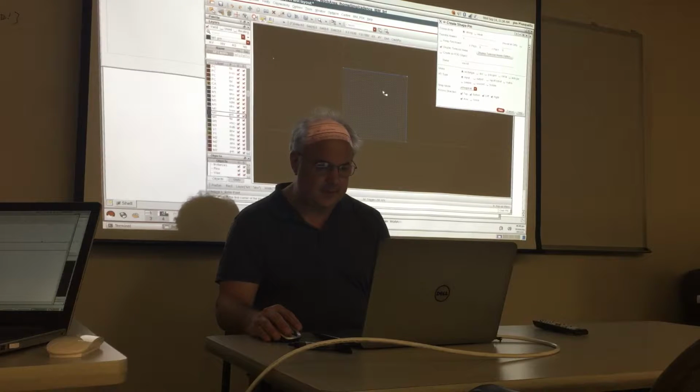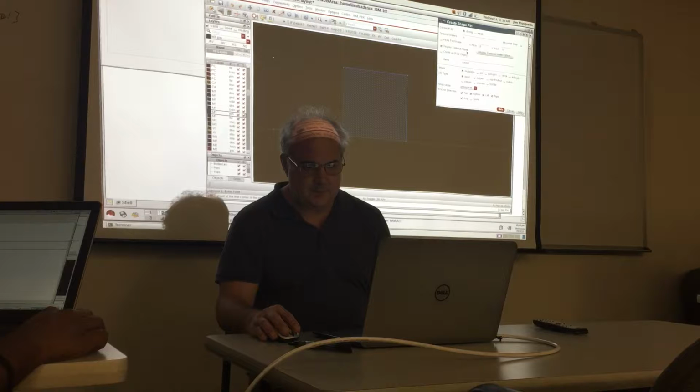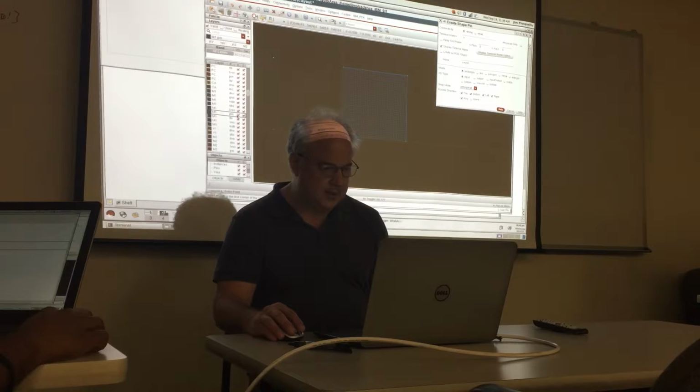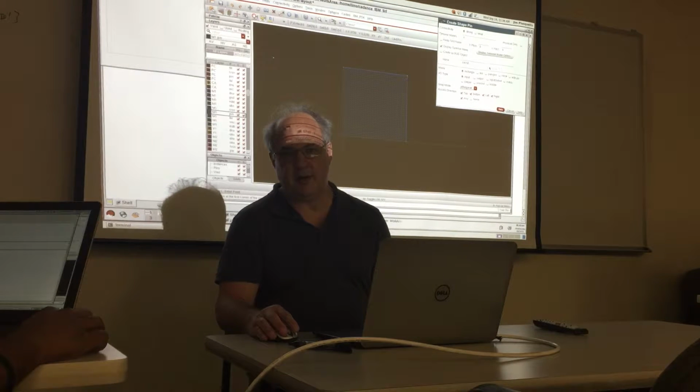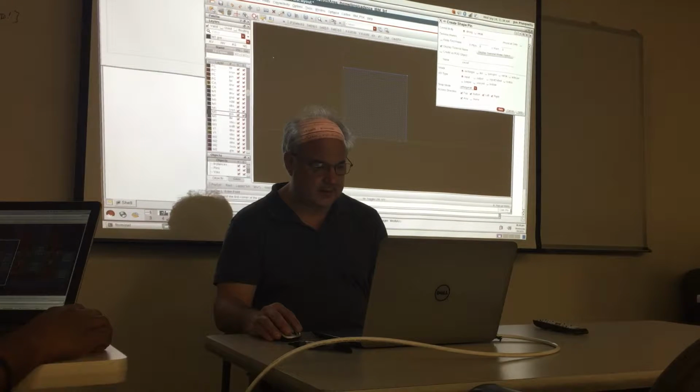Okay, if you screw up the font size, you can fix it. If you screw up the LBL, I don't think you can. Okay, and then make sure display terminal name is turned on, and then you're almost ready. So you got the input, you got the name, you got the display terminal, you got this layer selected, and you've got the proper LBL layer selected inside the display terminal name option. Now you're ready to click and then drag. Okay, and you drag the pin over, and then you want to put this guy as close to the middle as possible.